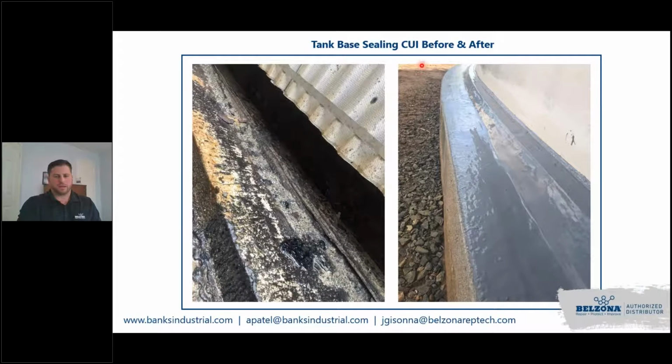Tank bases, we talked a little bit about this earlier. Anything that's insulated and anywhere there's going to be a break and any tank that's outside, water will find its way into the tank. It'll break apart and saturate the insulation, and it'll begin to work its way down to the bottoms and bases of tanks. So as you can see where the laser pointer is pointing out right here, tons of scale buildup and even potentially through holes. And this is really not a good thing for customers.